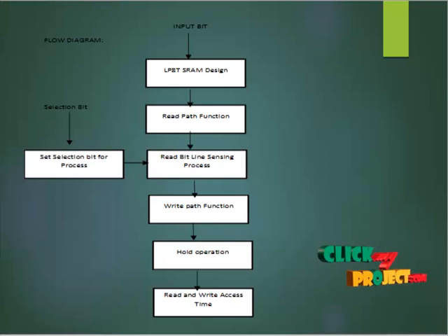In our project, we compare with eDRAM cells for main memory access. The speed of memory has had a large increment, and there is a gap in performance capability. We reduce the supply voltage, so dynamic power decreases and first order leakage power decreases, and at the same time we operate the cell in the subthreshold region, with the supply voltage lower than the threshold voltage.